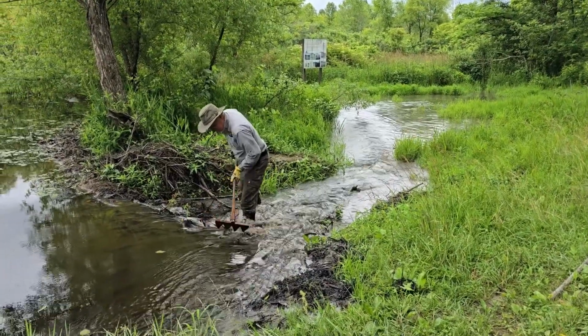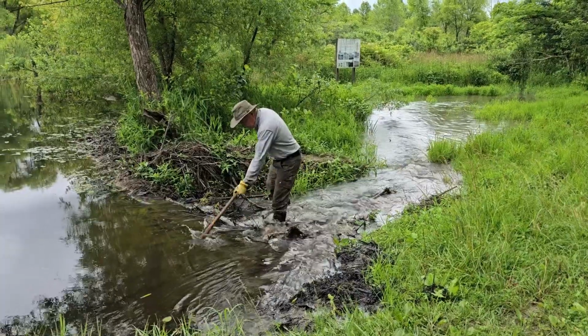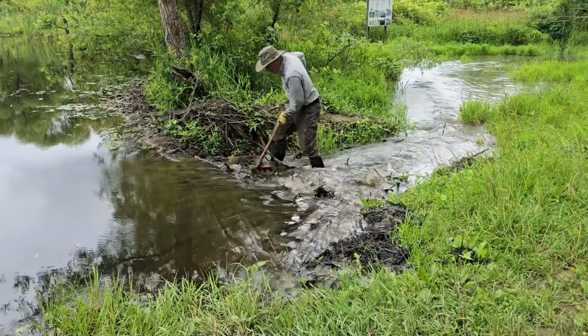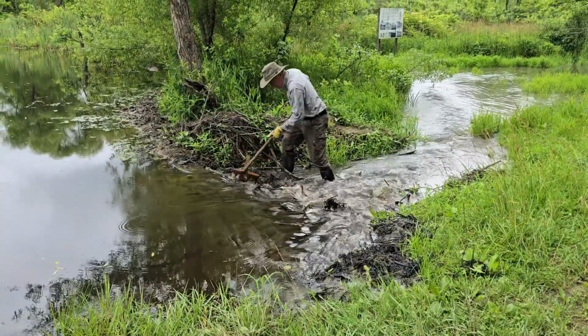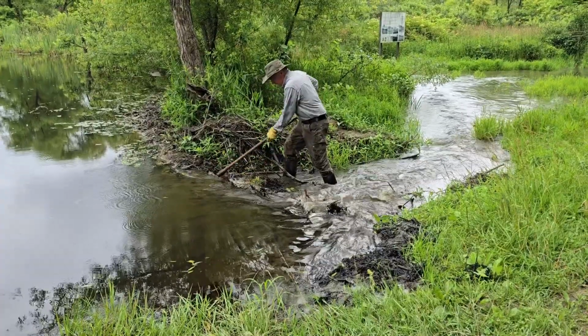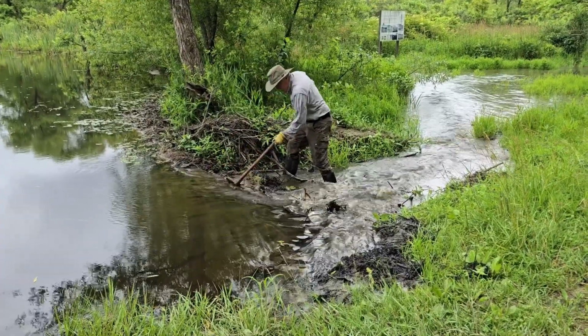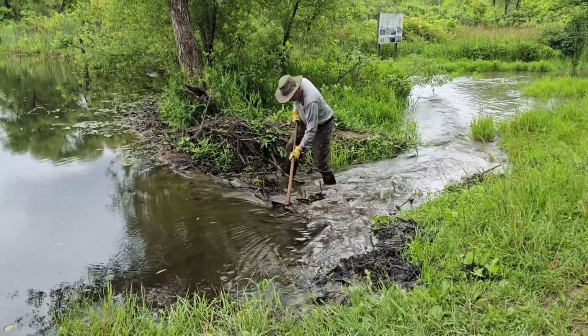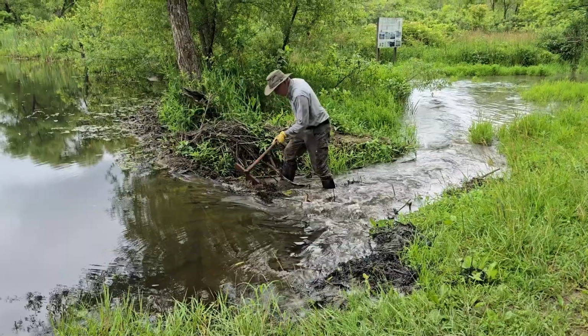The long-term solution would be to change the spillway into a permeable rock drain. To do this, we would need to remove the beaver dam using an excavator and then fill the spillway with a thick layer of rock the size of footballs. Water could flow out of the wetland in between the spaces between the rocks where it would be more difficult for a beaver to detect and to block.